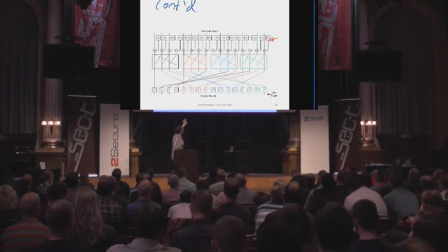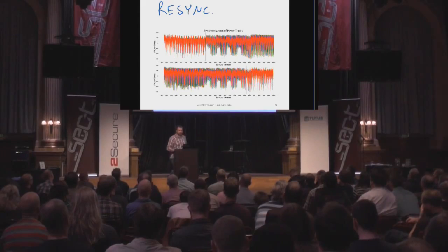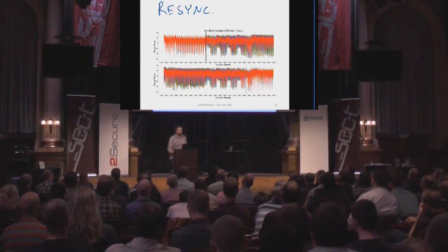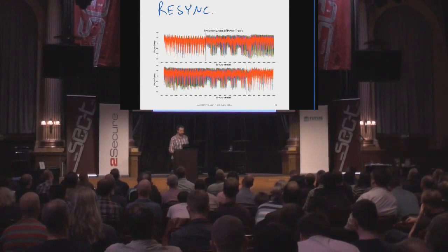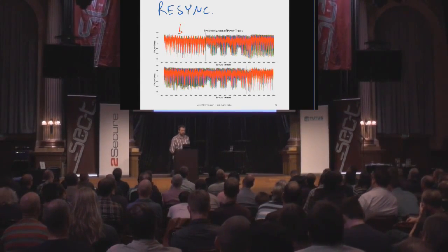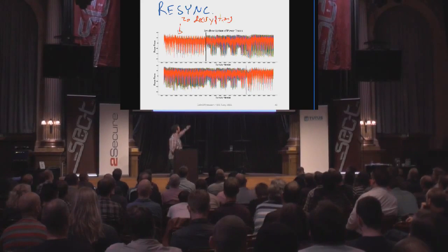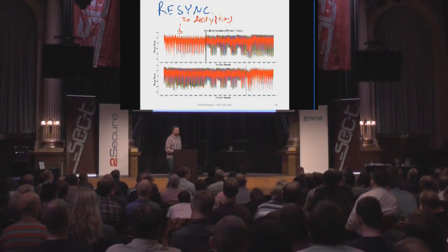There's a tiny bit of complexity when you physically do it. In this case, the AES implementation, I'm using one from the app note. It works fine for that first 16 bytes, so they're very nicely synchronized. So this is like 20 decryptions. I've sent it 20 blocks, and I'm viewing the power consumption.